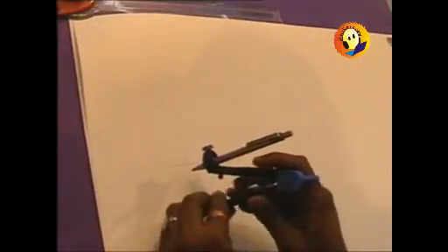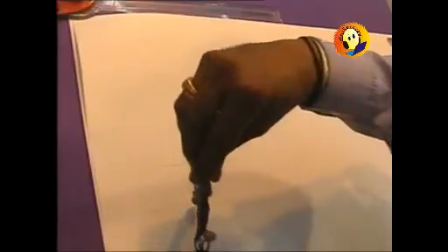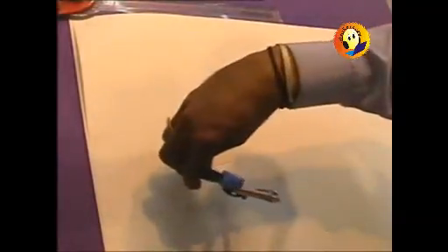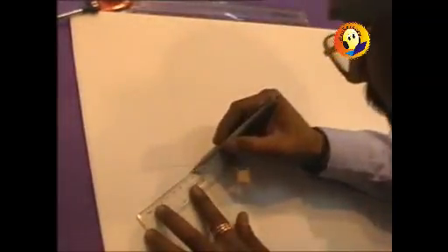Now, to draw the hexagon, we will have to start with the circle. As the side of the hexagon is given to us as 40 millimeters, we will be drawing a circle of radius 40, onto which I am required to draw the hexagon. Now, as the hexagonal pyramid is resting on a triangular face, the rotation of that hexagonal pyramid will be taking place about the side of the base. So we are required to have the side of the base of that hexagonal pyramid perpendicular to XY, because that will work as the line of rotation.